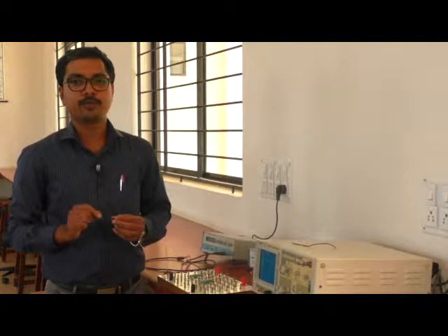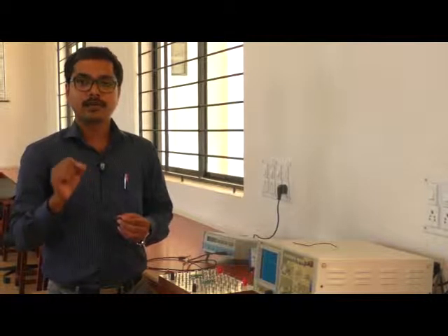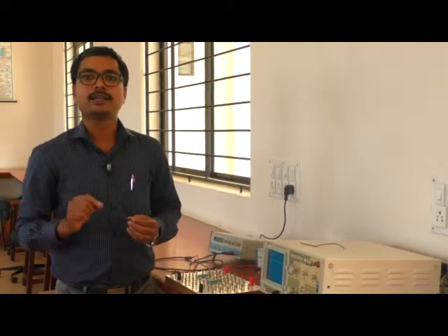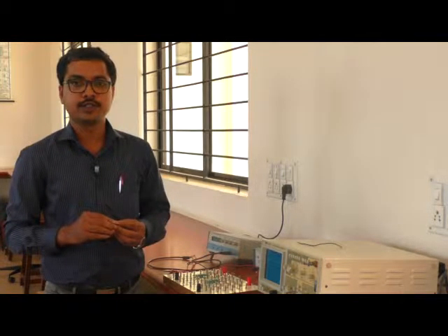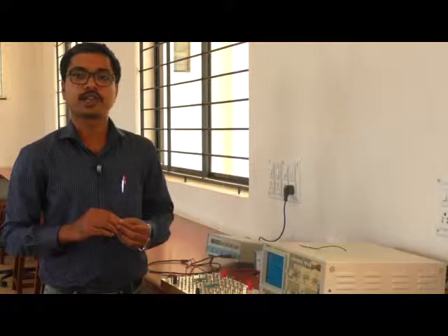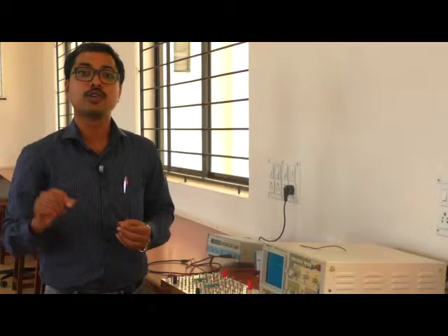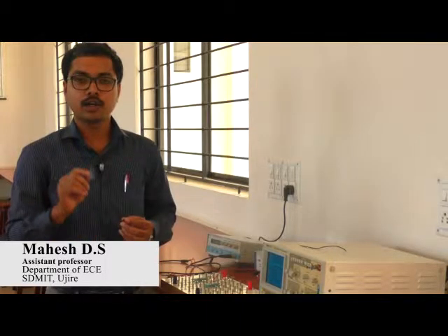The basic equation of the operational amplifier says that voltage gain AV is equal to 1 plus RF by R1, that is 1 plus feedback resistance divided by the input resistance. To convert that non-inverting amplifier concept into the voltage follower circuit, we have to take the resistance RF equal to 0 and the input resistance R1 equal to infinity, so as to make the ratio 0, that is 1 plus 0 equal to 1. Altogether, voltage gain AV is equal to 1.